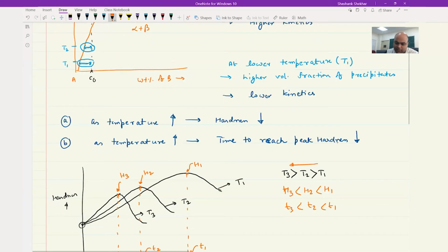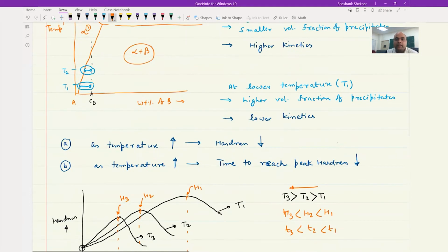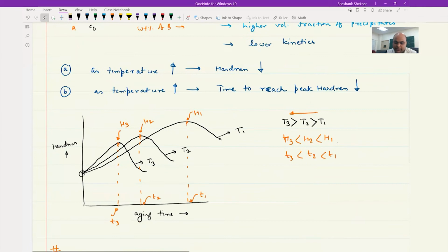So if you see here, based on the phase diagram, the equilibrium structure is alpha plus beta, isn't it? So if you go to the alpha region, single phase region, and do solution treatment, you could have slowly cooled it and formed alpha plus beta. Why do you want to quench it first and then age it again, wasting some amount of energy by heating it again? So what is the necessity of quenching it rather than slowly cooling it after you have solution treated the alloy?